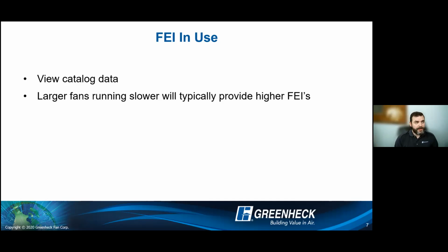Kind of mentioned this earlier. The larger, slower fan, many times you can get to a point where it's too large and running too slow, and your FEIs will again drop. But it does encourage, you'll hit those higher numbers above 1.0 typically when you select a larger fan.